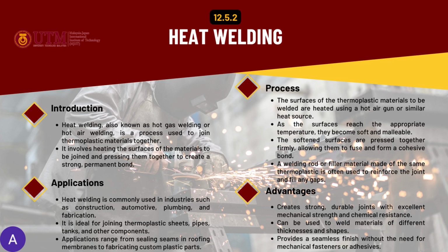So the working process for the heat welding is the surfaces of the thermoplastic materials to be welded are heated using a hot air gun or other heat source. And then as the surfaces reach the appropriate temperature, they become soft and malleable.